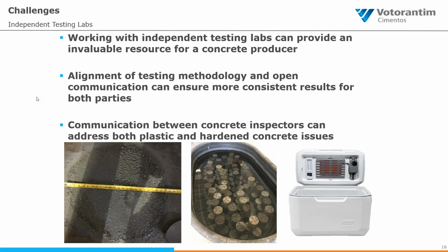The biggest challenges in our experience in producing this type of work are the contractor and the testing lab. You have to be very careful when you cast these specimens. It's much more sensitive to movement, to initial curing, to storage and handling than a compressive strength specimen.